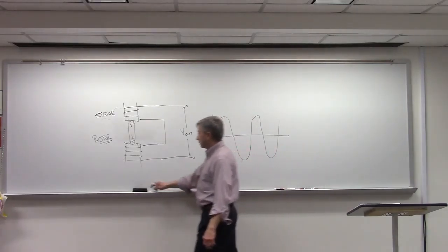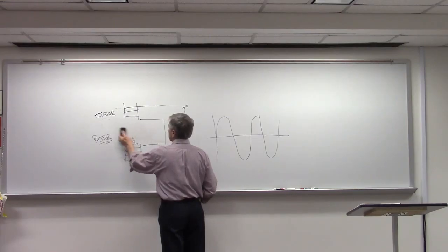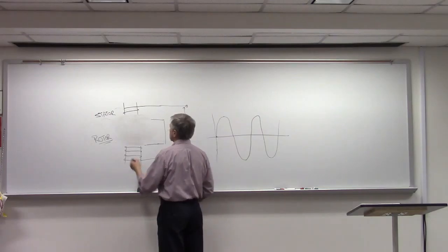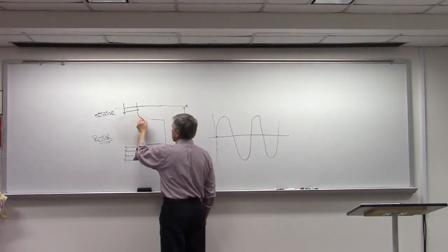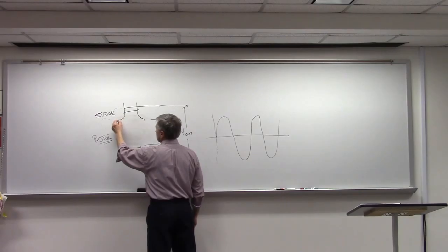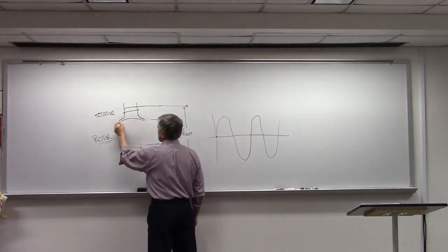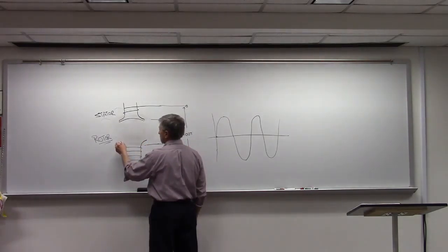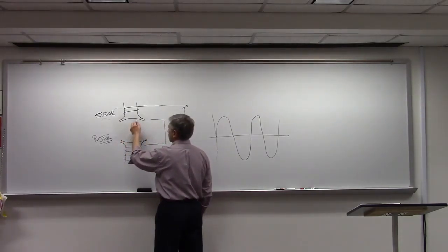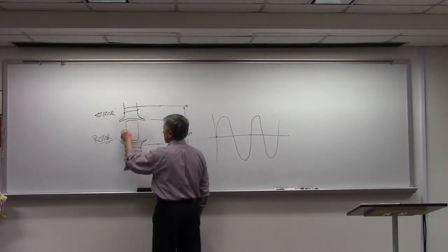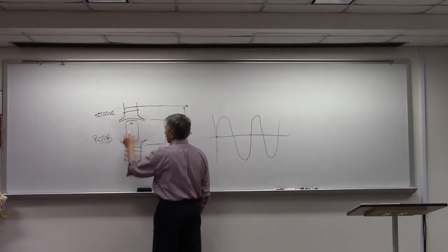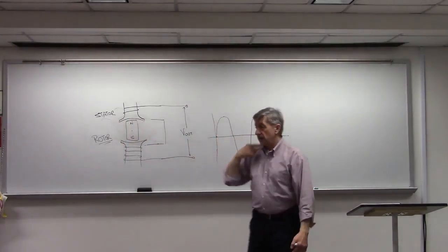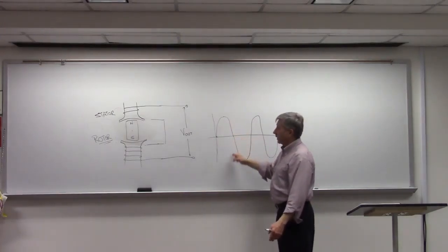And what they did was they changed the stators, and this is the way generators are today, to make them flared. So the poles on a generator kind of look like this. And this guy is what looks like that. And then you have your rotor like so. And so the idea is when you put wings on each one of the poles, the vertical transitions are not quite as vertical.